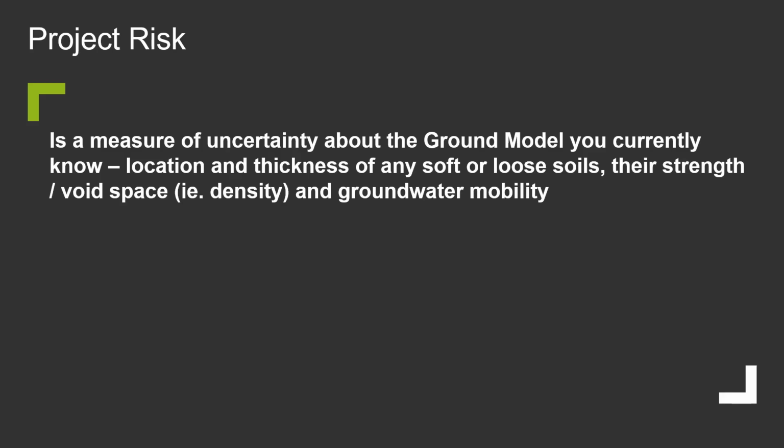So we're really trying to determine what soil's there, how uniform is it, what's its strength, what's its deformation characteristics, how is it going to behave, and then can we model it well? Is the groundwater mobile? Will that cause us difficulty during on-site excavations? Will that cause a strength reduction? Is it going to be difficult to control it? Will the groundwater have contaminants within it? There's lots of issues and questions that come out of this.